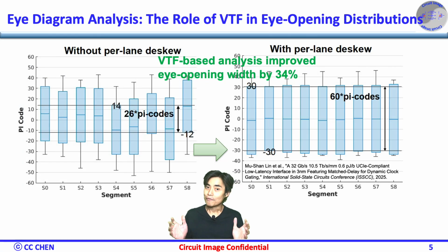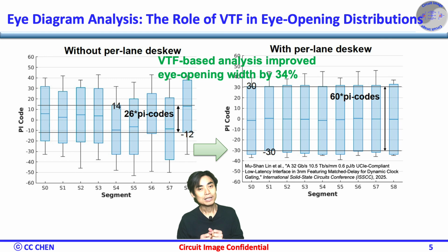Measured data from ISSCC 2025 UCIe experiments demonstrate how VTF correlates directly to eye closure effects. A study on parallel skew correction shows that VTF-based analysis improved the eye opening width by 34%, significantly enhancing bit error rate performance compared to traditional frequency domain assessments.